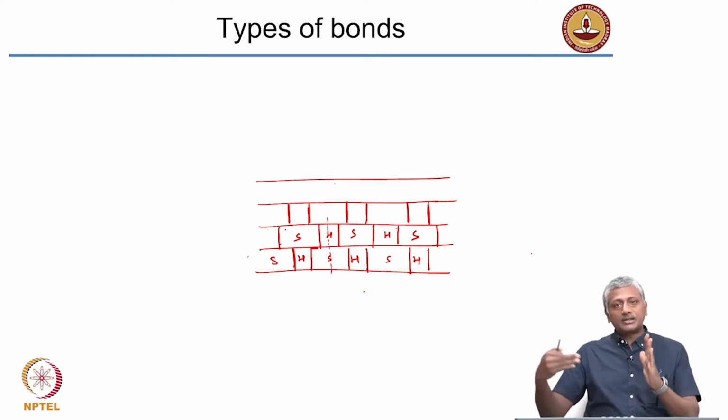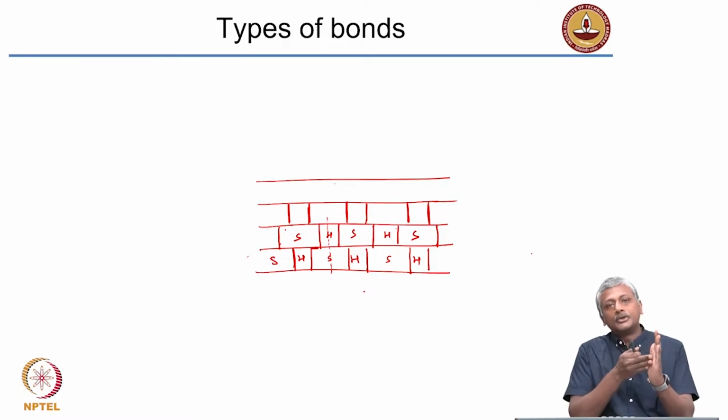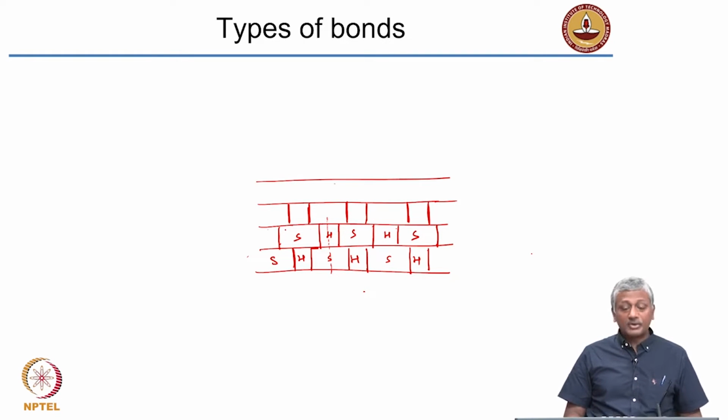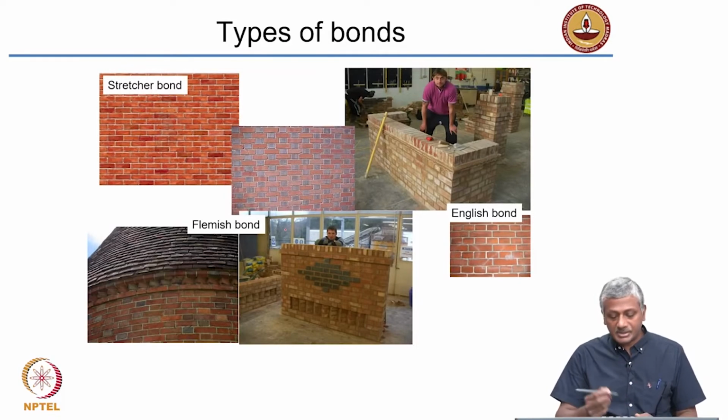The problem is when you start coming to the end of the wall at the corner, you will have to make arrangements of using brick bats, and that's a little bit difficult because when you start putting brick bats in it, you increase the amount of mortar available and that causes the wall to be weaker. Okay, so Flemish bonds are generally weaker than English bonds, but nevertheless they are most aesthetically pleasing. So this is just an appearance.